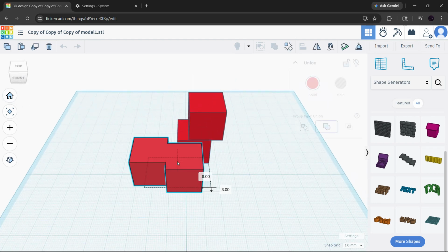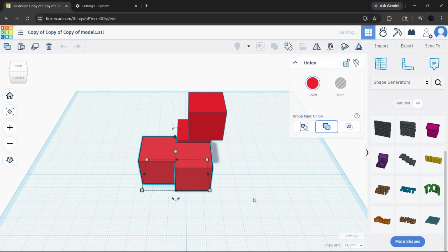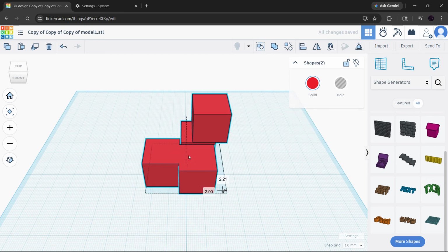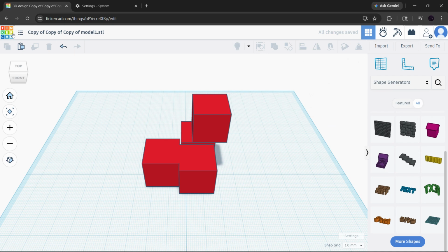So, to quickly recap, if Tinkercad gives you a grouping objects error, try nudging touching shapes, simplify nested groups, move the model to the center of the grid, group in smaller batches, duplicate the project to clear the session cache, and check for broken shape generators. In most cases, one of these fixes will solve the problem right away.